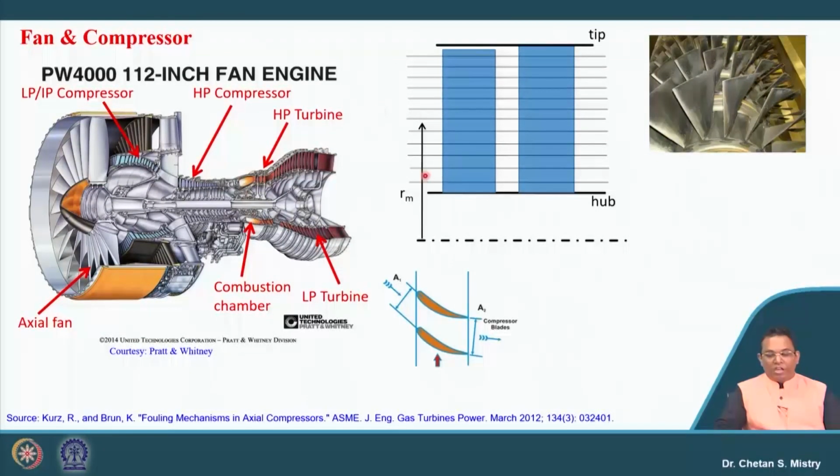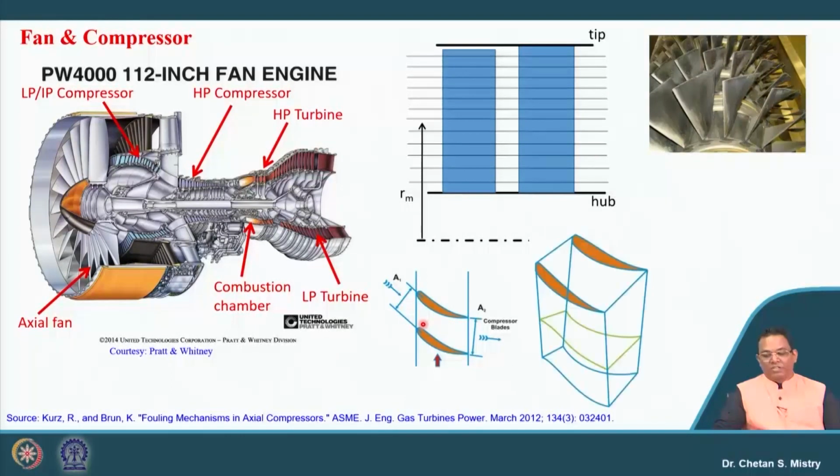Okay. Now, here at one station I will be putting that as, say, a section. So, here if I cut, it says this is my passage, and overall if I look at the whole blade passage, it is made up of this diffusing passage. So, that is where we are having the diffusing action, which is because of rotation as well as the passage area between two blades.